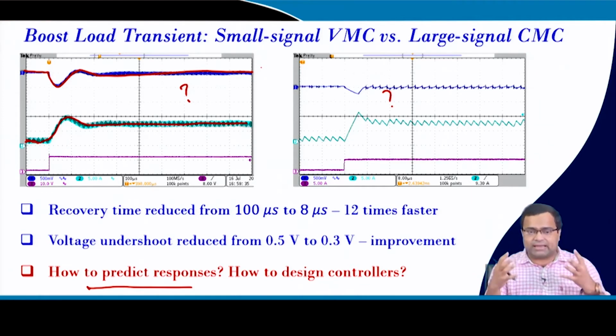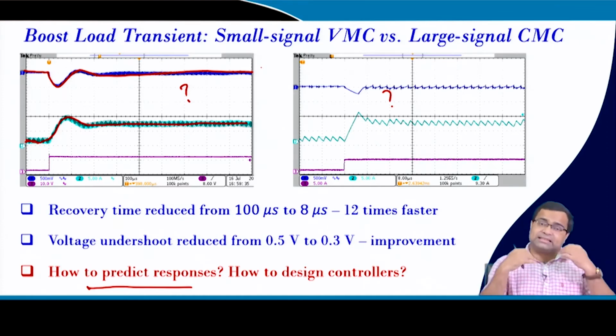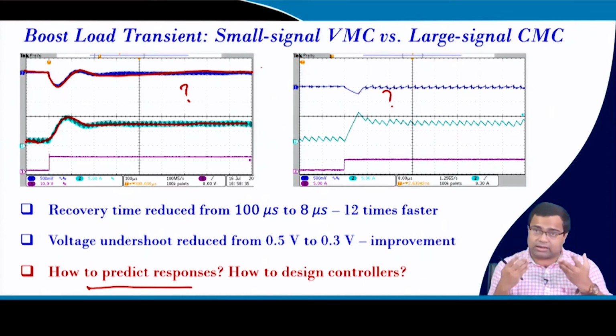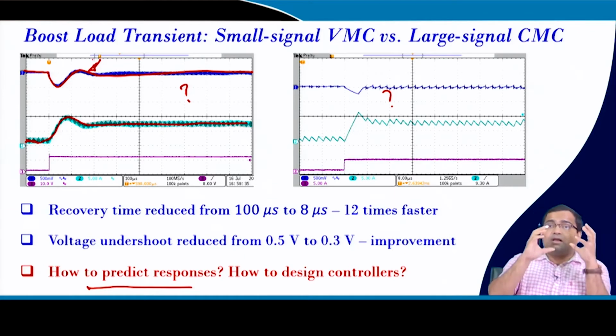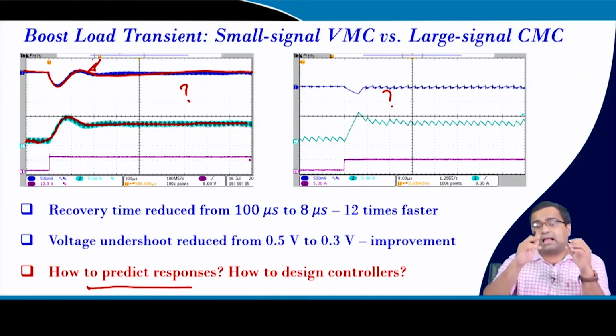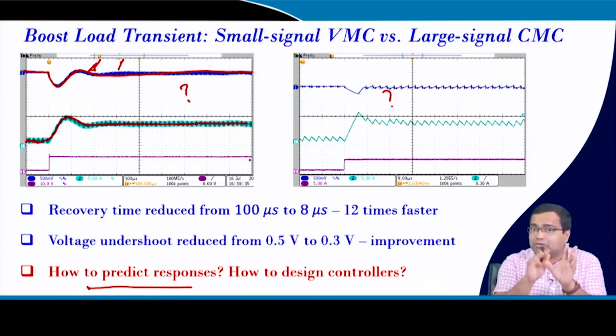That means, whenever you design a converter, first we design using the small signal model, derive the transfer function, design the controller using our linear AC model, then get the AC transient response using that linear model, add the operating condition, and then compare with the actual switching simulation, and you will see something similar. The red line is the result obtained from the linear model, and the actual switching converter is the blue trace, which we will compare in the subsequent lecture.